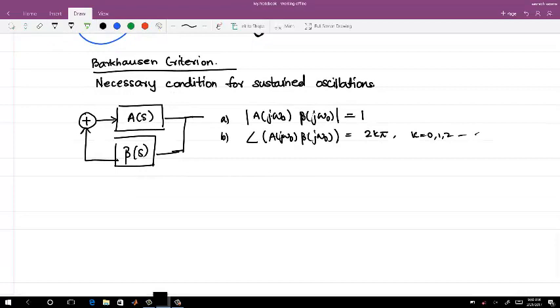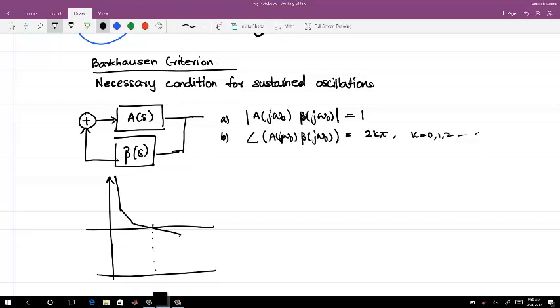You can have a gain greater than 1 and a phase more than 180 degrees. When you start with a two-pole system, the phase is greater than 180 degrees, and then you have a zero where you have a loop gain equal to 1 and a certain phase margin, right? So for a two-pole system or a type 2 PLL, you see. Let's consider another pole in the system, 3 poles in the system, that becomes much better. Okay, so then like this and like this. So if this is the loop gain of the system, right?